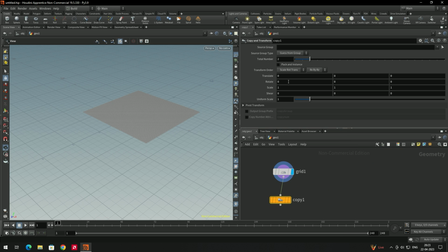I want to change the directions of the cloths individually. For example, I will make a rotation of like 15 by 15. I will enable this. And also I will set the number of copies, let's say 4. And here we can put the offset. In order to put this offset, we will use this translate option. We're going to move in the y-axis, so let's say in this way.